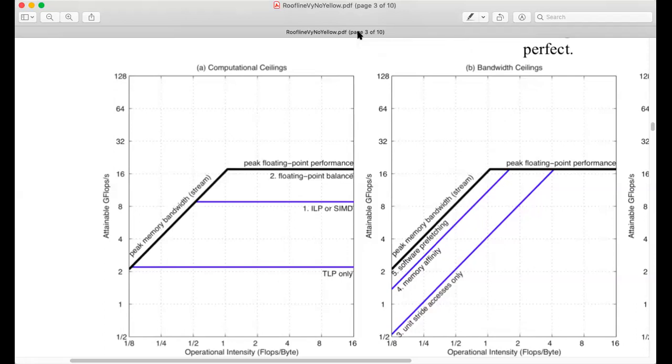But if you have a SIMD of 1,000 additions per second, but the memory is not able to supply 1,000 elements per second, then what's the point of using that many resources on the FPGA? Let's say the max you could do is 600 additions per second, in which case you can reduce the loop unroll factor to 600, and that way we hit the ridge point.